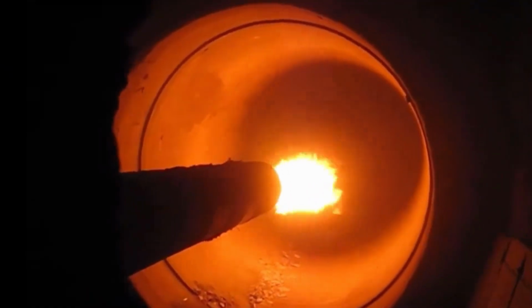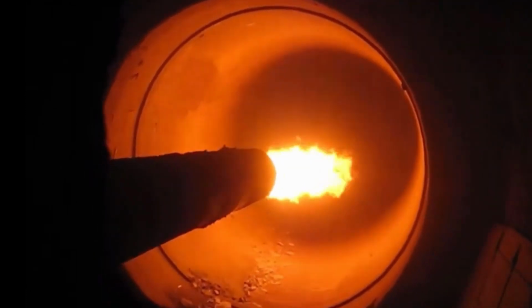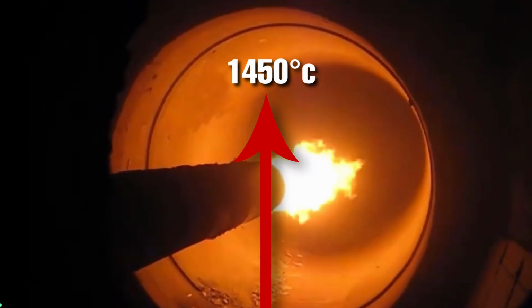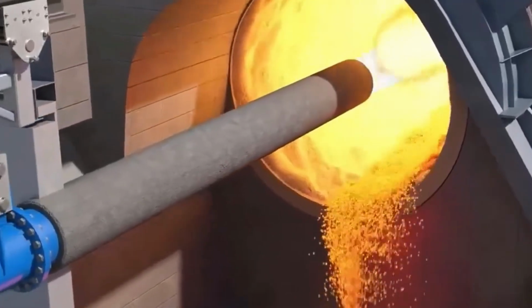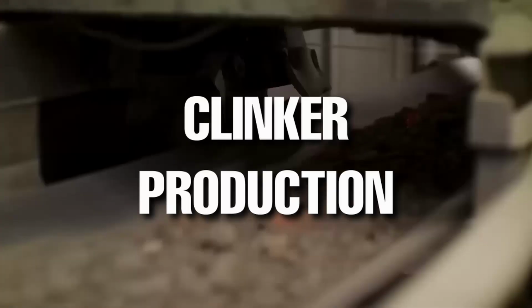Fuel is fired directly into the rotary kiln at up to 2000 degrees Celsius to ensure that the raw materials reach temperatures of up to 1450 degrees Celsius. The intense heat causes chemical and physical reactions, leading to the formation of clinker. Clinker production. The raw meal is partially melted in the kiln, and as it moves through the kiln, it is transformed into clinker, which is a nodular material.